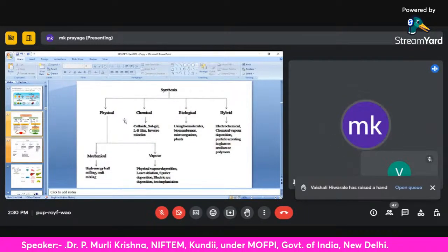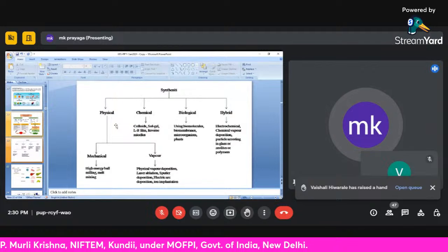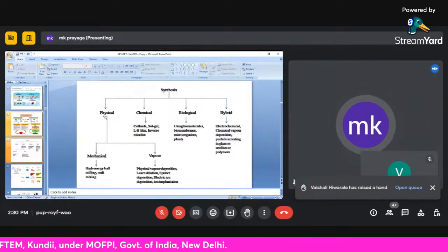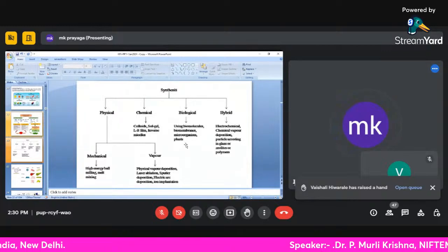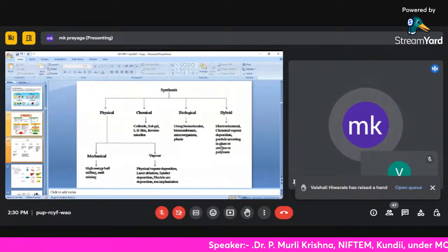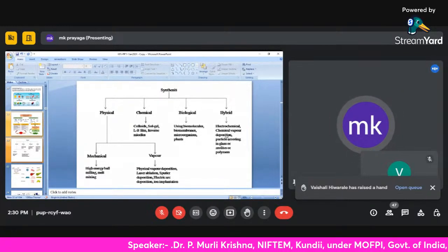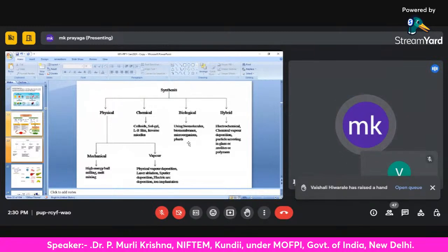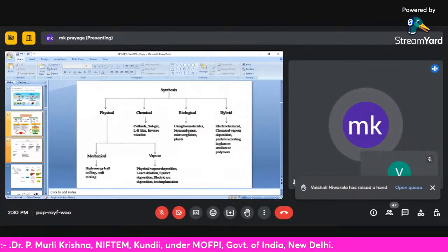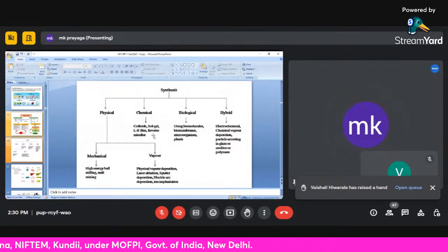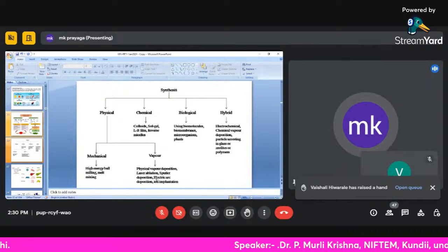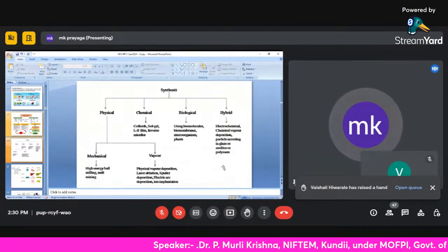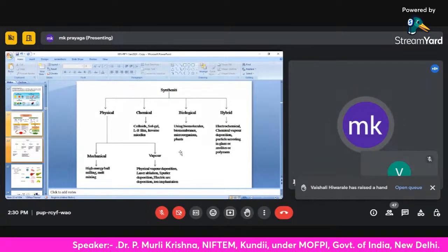So there are four different methods available for the synthesis of nanostructured materials. You may select physical, chemical, biological, or hybrid methods. Nowadays, even bacteria and phages are generating these hybrid structures. And biological, you can find with microorganisms; nanoparticles can be synthesized. And chemical and physical: ball milling, melt mixing, and physical vapor deposition. And of course, chemical vapor deposition comes in the hybrid method.